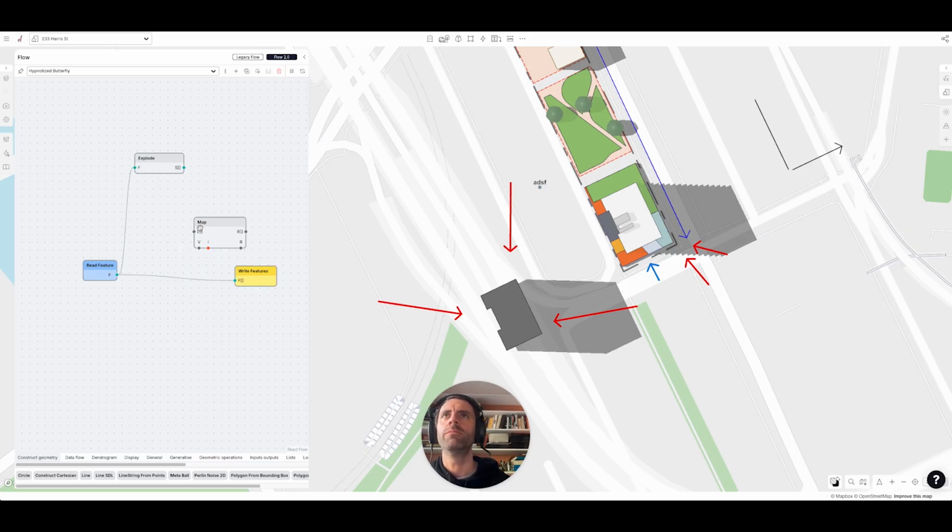So what I'm going to do is map over them and measure a vector angle between 0, 1, 0, which is y, which I'm assuming is up the page, and the normal, as in orthogonal to the tangent of each polyline, each line segment. And so we use frame, because if we deconstruct it, it has the origin and the x and the y and the z. So it's got the normal, the tangent, and the z for every point on the frame. And we'll do it, I don't know, 3 meters down the line.